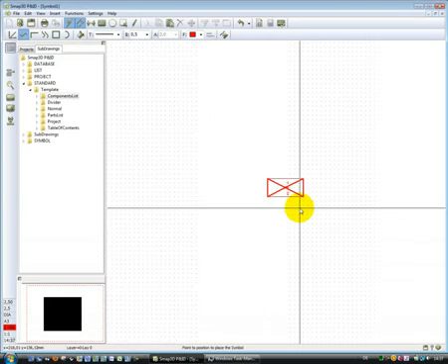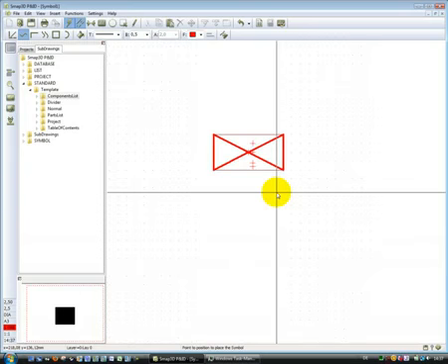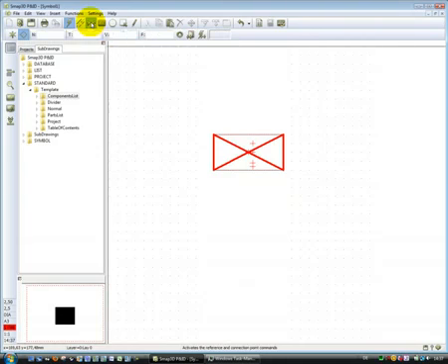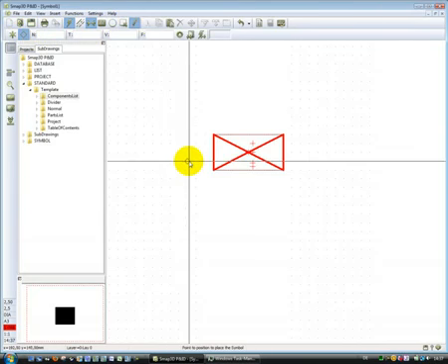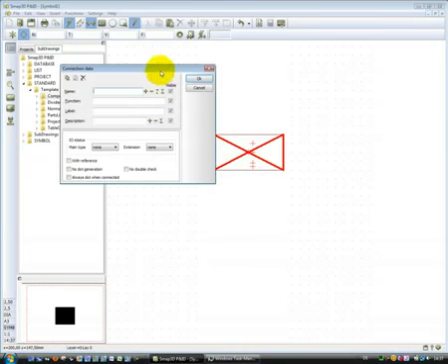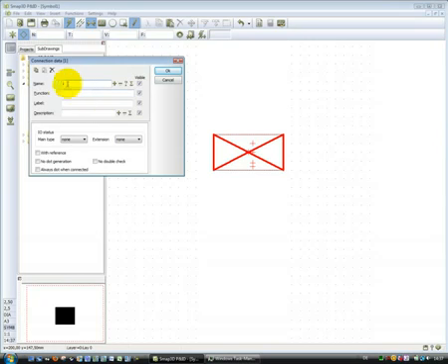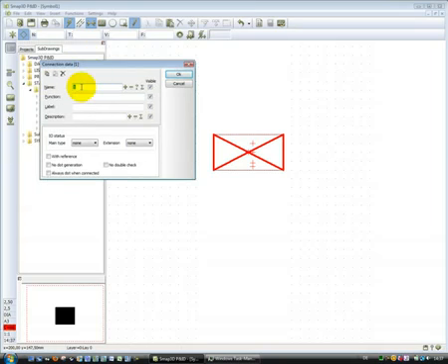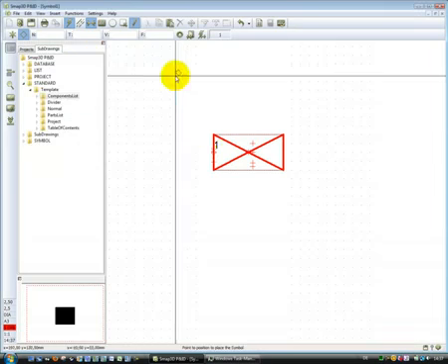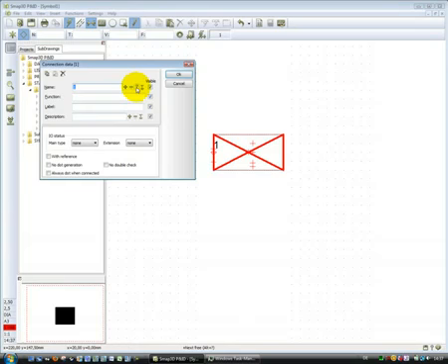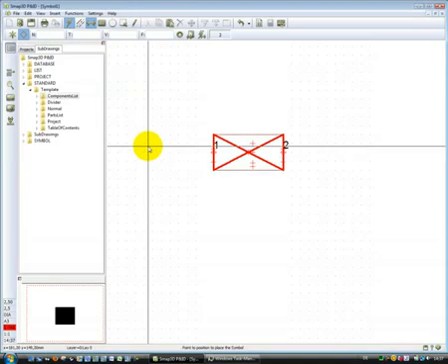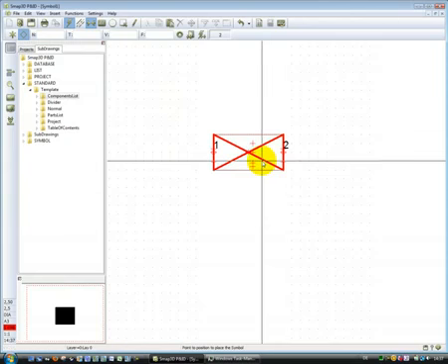At the next step he has to create the connection points. The connection points must belong to the symbol, and the connection points identify the point where it's possible to place a line or a pipeline. I have to place these connection points on the symbol geometry, and I have to name them, because normally the connection points on the real component also have their numbering. So I can say this is symbol 1 and this is connection point 1 and connection point 2. If this is done, I now have created my symbol.